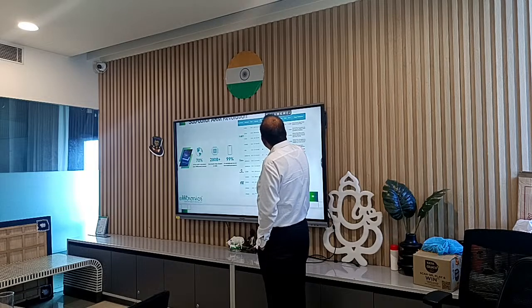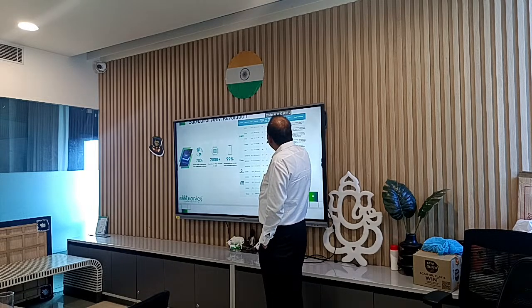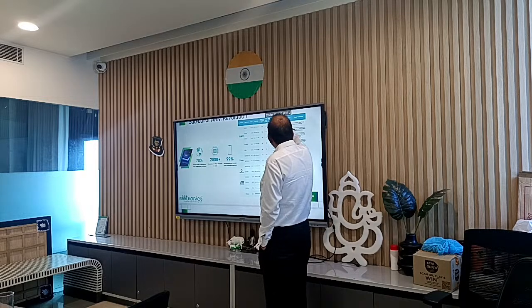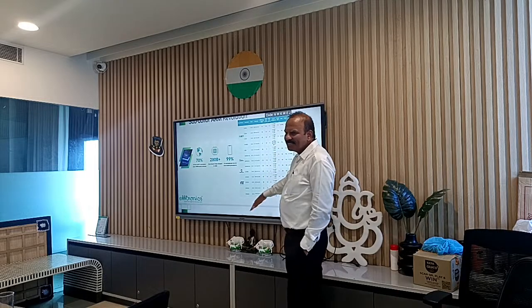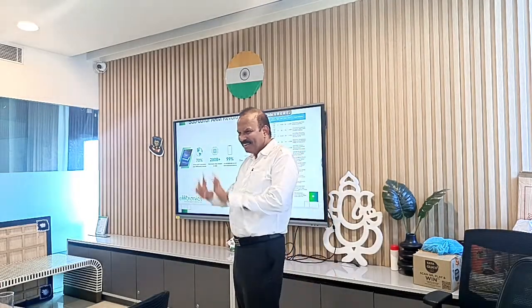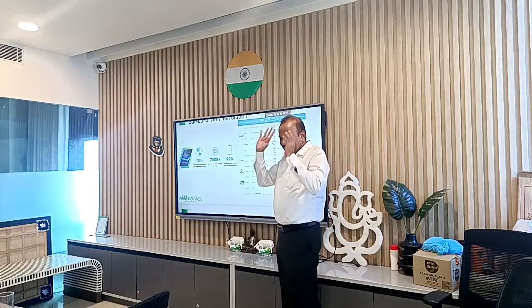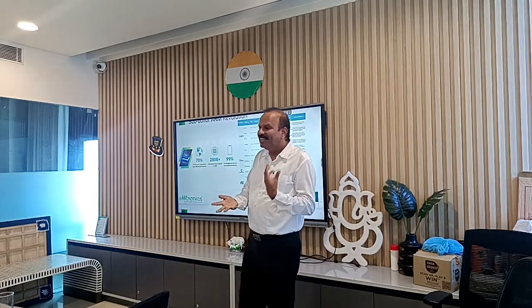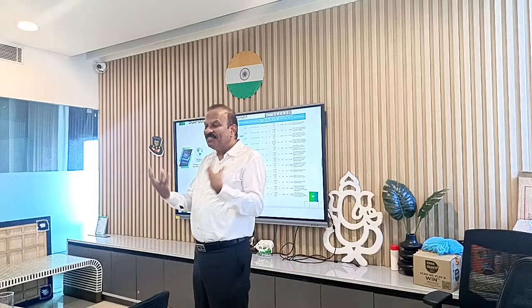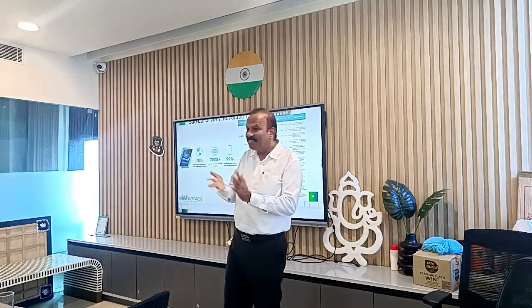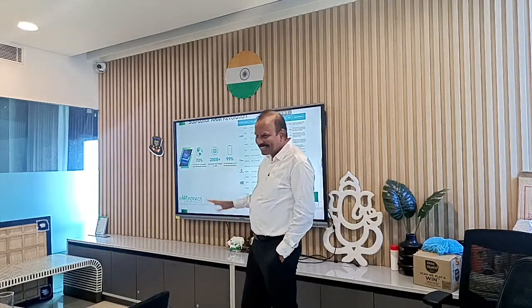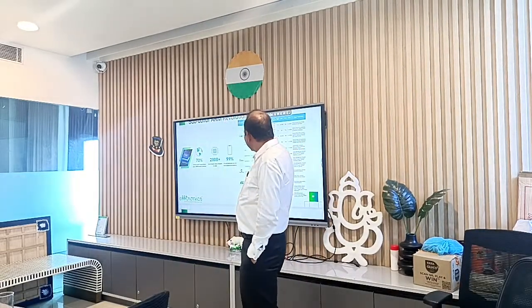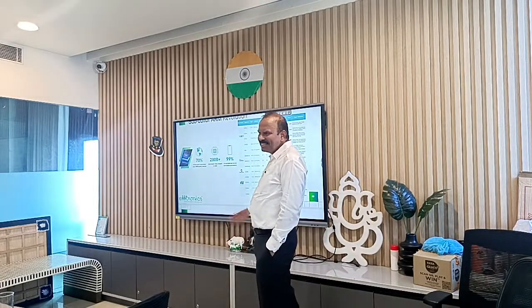Of course, these chips specify how many megahertz they run at, how much flash and RAM, how many ADCs, DACs, PWM timers and communication ports there are. So everything is available in the same chip and you need not struggle for it. Initially, when we used to work with the 68K and all, connecting each peripheral was a nightmare. All timings had to be taken very carefully, and if the timings mismatched, it didn't work. Even today that challenge exists, but now everything is inside, so I need not worry about it. Easy to make.